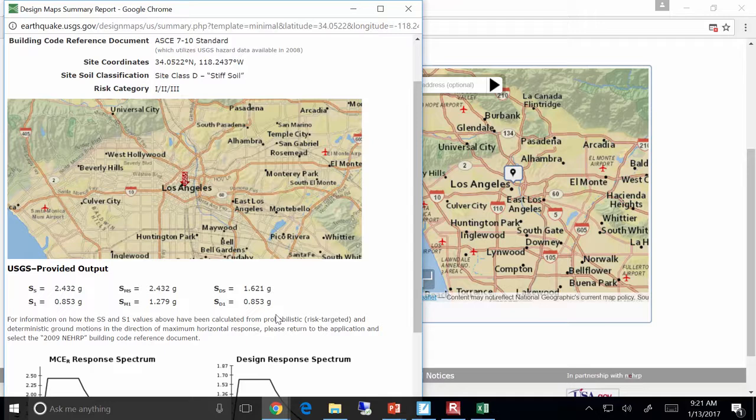A very common structural fuse in the world of steel design is what's called a reduced beam section. The idea is if you've got a frame with beams and columns, which would you want to fail first, the beams or the columns? The answer is the beams, because if the columns fail, that's the whole building. If the beams fail, well, it sucks, but it's just that one element.